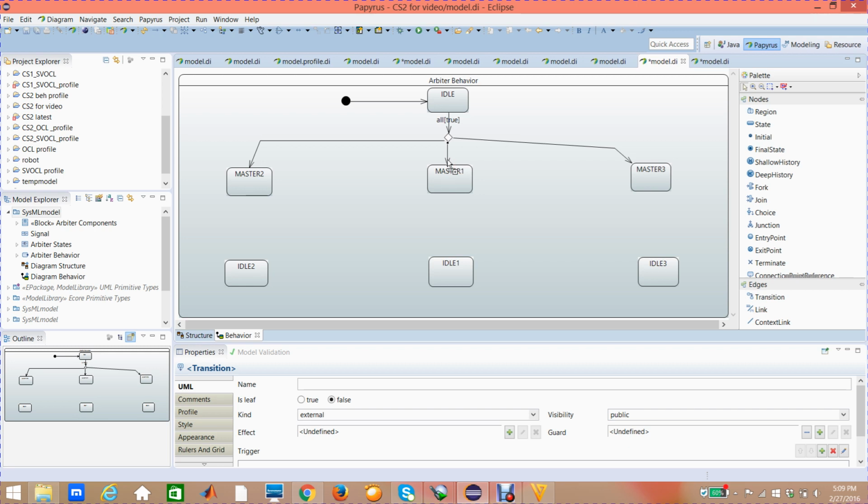So to add a trigger, this means that the system will be triggered on the request 1 port, and the condition on that port is that request 1 is false, because request 1, request 2 and request 3 are also active low, which means that the request will be considered true when request 1 is false.